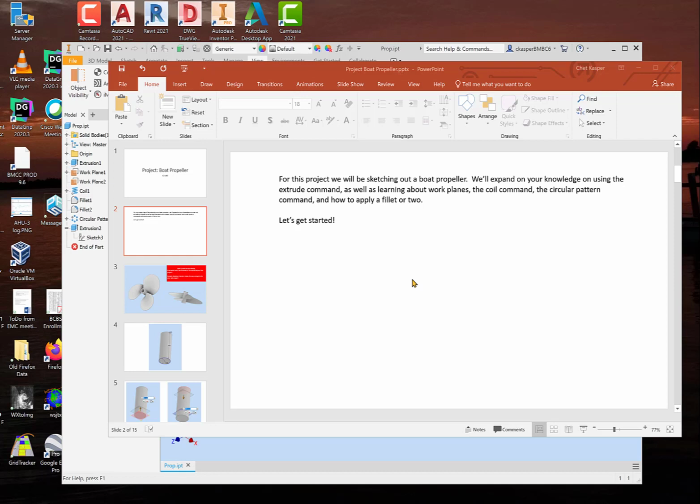And the fillet command, which is something you'd use a lot if you're designing something in industry, because fillets are basically a way to soften sharp corners. And if you do any kind of drafting where the project is going to end up being injection molded, fillets are very beneficial for getting them out of the mold. You'll see then a lot of plastic products that are cheap. They basically fall out of the mold or are just pushed out of the mold because of the way they're designed. And that explains a lot of why there's lots of soft, no sharp corners whenever they can help it.